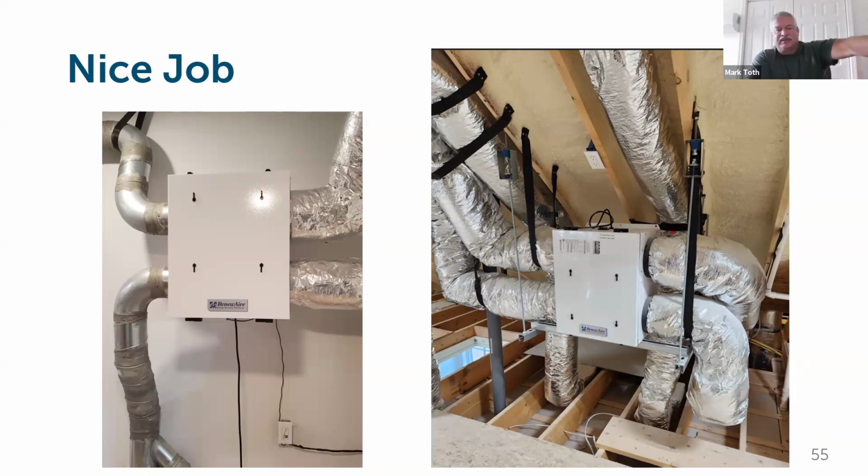Those are the two going to the interior of the home. We put about 3 feet of flex to replace those elbows, and the system was absolutely 100% silent. Nothing changed except that hard duct was decoupled from the unit, and it was very, very quiet. One on the right, just a classic, really good looking install.